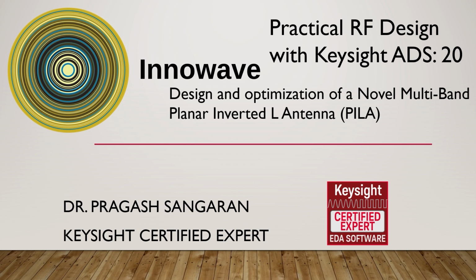In this tutorial, we will learn the complete design and optimization guide for a novel multiband planar inverted L antenna. This antenna is implemented on a rigid printed circuit board. This antenna covers 617 MHz to 960 MHz, 1.71 GHz to 2.2 GHz and 2.3 GHz to 2.69 GHz.